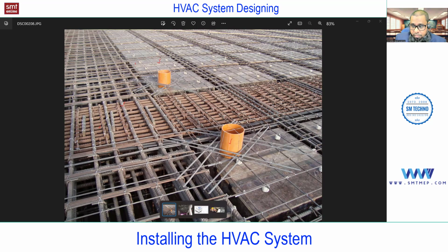In the shop drawing, the contractor is going to mention the length. I think they're going to mention it. Yeah, in some projects you'll find the length also, but not commonly. Even if it is mentioned, the fabricator must verify. And nowadays in actual practice, say 5 or 10 years back, the fabrication was on site, but now it is factory fabricated. Okay. So they must verify the drawing with the scale factor.